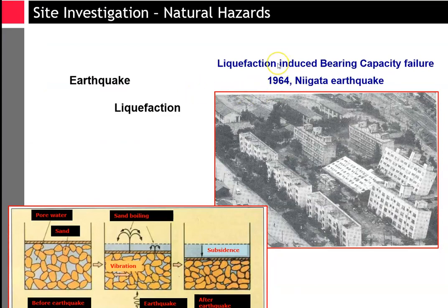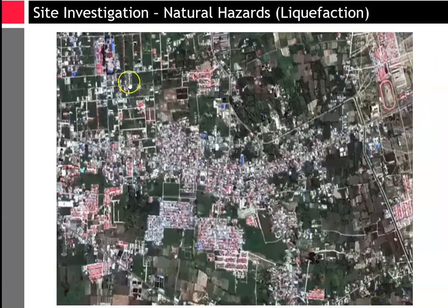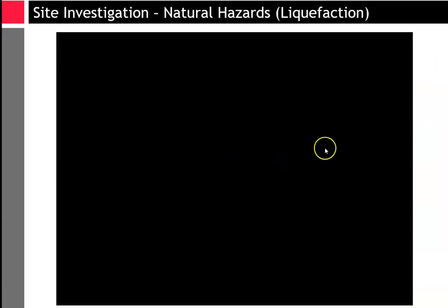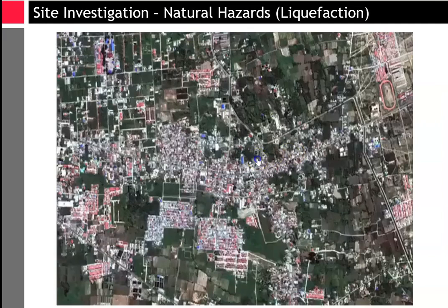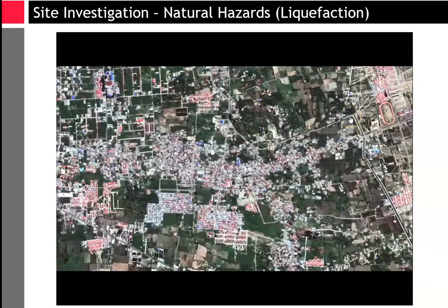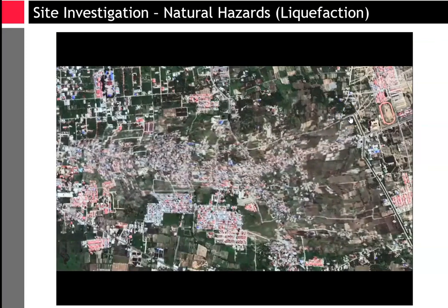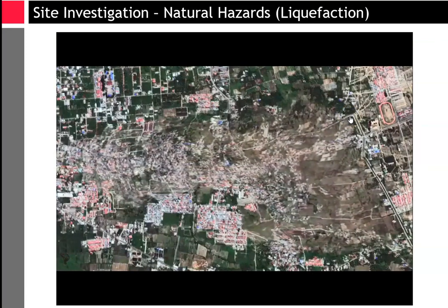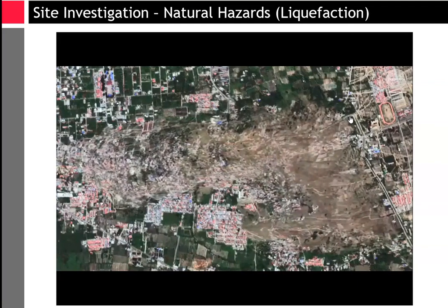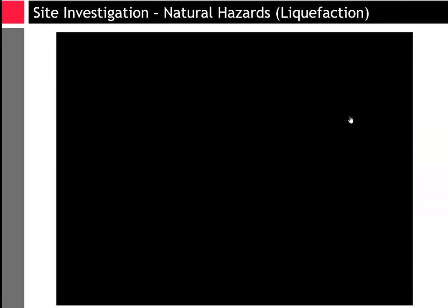We may also have problems like this one, which is known as liquefaction, which happens in sandy soils. We're going to discuss it when we are in an earthquake-prone area. Liquefaction also could collapse and fail or cause damage to different types of infrastructure systems. So the white pictures that you see here, which are moving down, are structures above ground over there, or embankments or roads or whatever infrastructure systems that we have, which happen because of liquefaction.